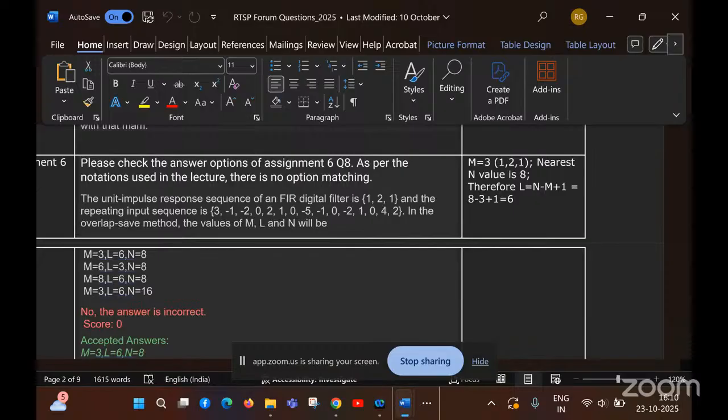Okay, so why it is a low pass filter is, as you can see, you have to look at your e power minus j omega. Depending on that, I think there was one assignment also to find the filter type, given h of n, and given input x of n, how to find what kind of filter it is. So you can go to the z domain and check, or in the frequency domain, e power minus j omega, you calculate the magnitude of that, and the magnitude is enough for you to check whether it is a low pass filter.